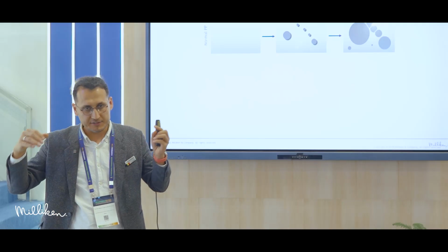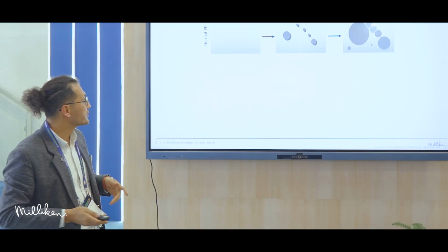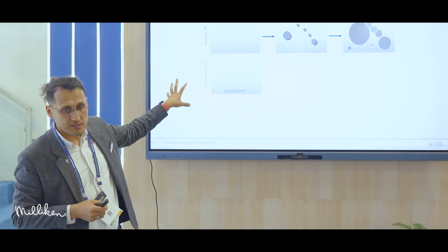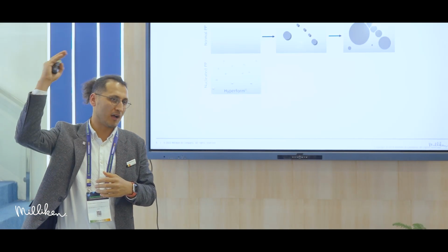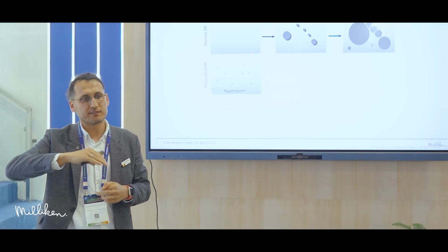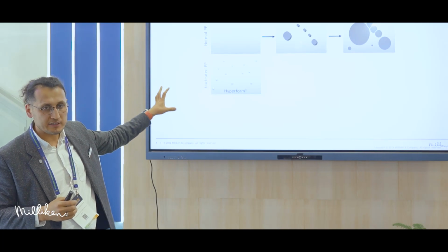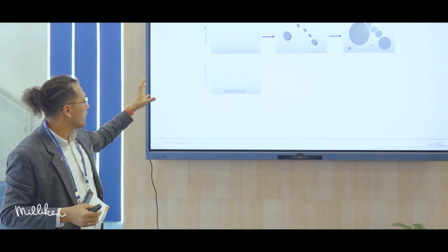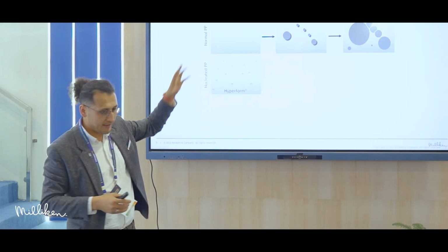The direction of that and how it's been aligned also affect the physical performance of that. So how the nucleator PP works is, in the resin, we put a particle that can withstand a very high amount of heat, a very high temperature, that does not melt, right? So when the PP melts, our nucleator particles will not melt, and we evenly disperse it in the entire liquid, right? So when you melt the PP, you will have solid nucleator particles in that.